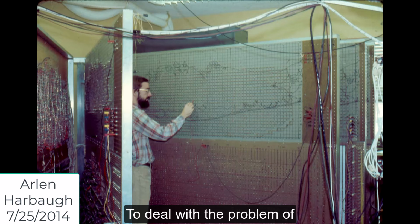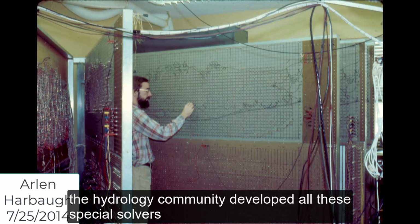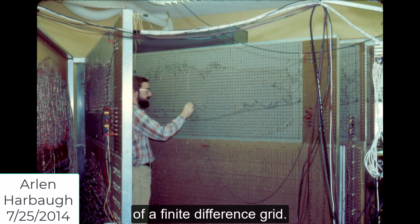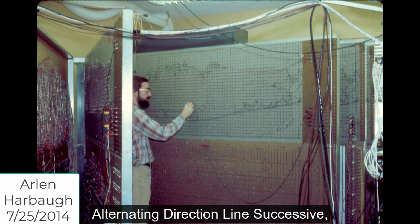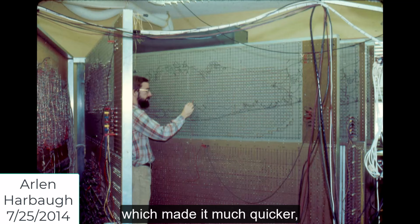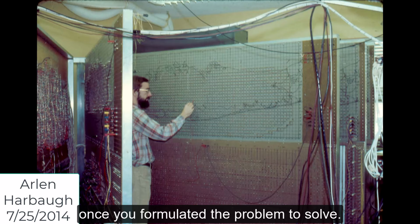Because to deal with the problem of computer resources on finite difference, the hydrology community developed all these special solvers that took advantage of the matrix structure of a finite difference grid, a regular matrix: line successive over relaxation, alternating direction line successive, and SIP, strongly implicit procedure, which made it much quicker and required less computer resources to solve these simultaneous equations than you could do with the finite element. So finite element just took a lot more resources once you formulated the problem to solve.